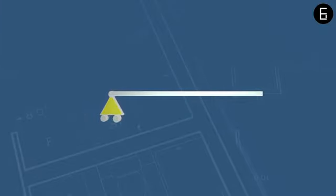A support with one unknown is restrained in one of the directions. A horizontal roller is free to move in the horizontal direction and rotate about the joint. It is restrained for vertical movement, and a vertical reaction would develop while resisting an external load. The designer would have to consider this and design the support to resist the force.